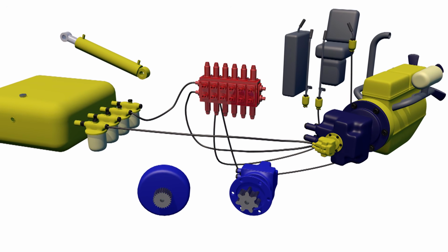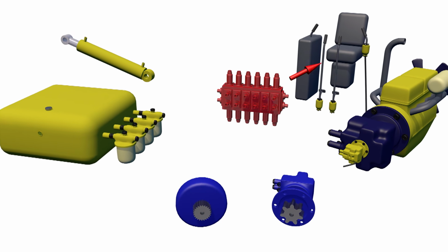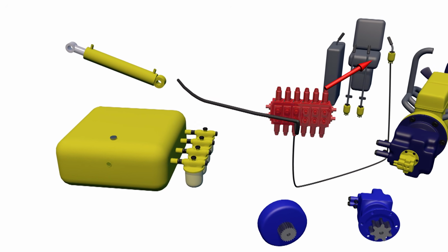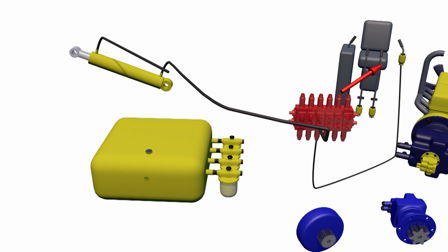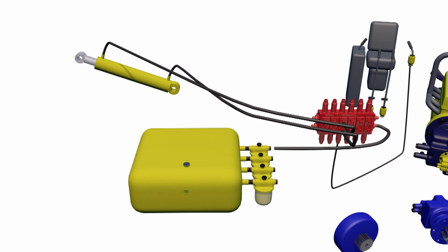The pilot oil circulates through the system or is shut off by a spool valve, preventing the high-pressure oil from actuating the working components. When the operator moves the lever, for example, to control the arm, the pilot oil flow moves the plunger in the spool valve and opens the high-pressure oil flow. The working oil flow presses against the hydraulic cylinder piston, causing it to move and forcing oil out from the opposite side of the piston.